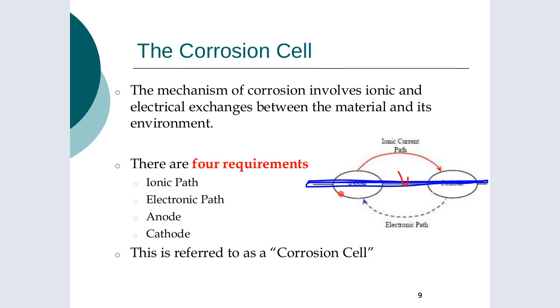And if you look at those disaster programs about what happens if humans suddenly vanish, they show how our mega structures will rapidly deteriorate and collapse due to the lack of maintenance and the corrosion that can occur. So just by putting in a film doesn't necessarily mean that you get protection from it. If there's any damage, you may have a very concentrated flux through the anode and a very high rate of attack.